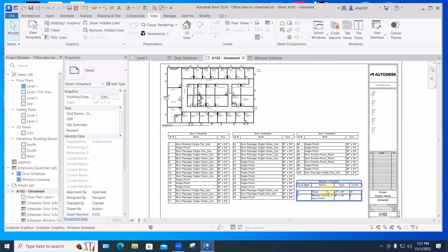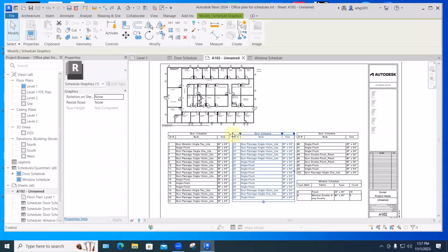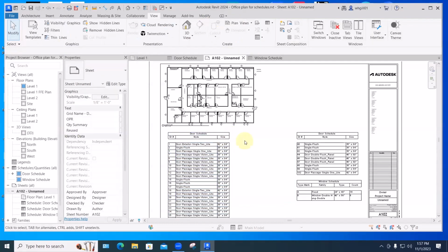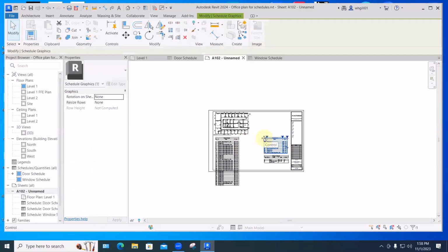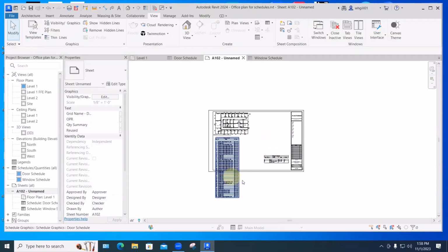If you want to pull your schedules back together again into one long one, like you've rearranged your page and you've got room for those, if you click on the second one, its move arrow right here, you can just drag that onto anywhere onto the previous one, and it will just add itself to the bottom and continue. You've got to grab that thing and just stick it on there.